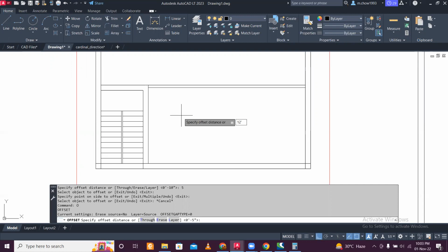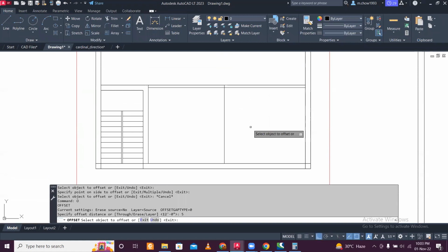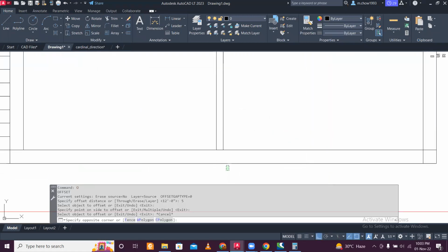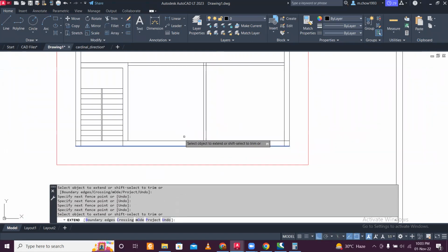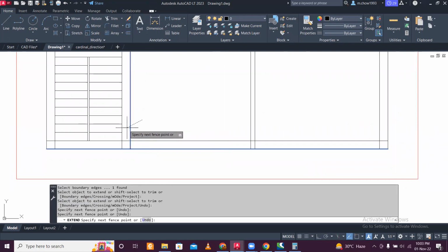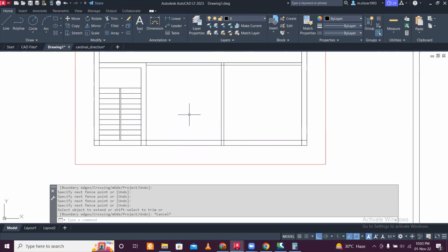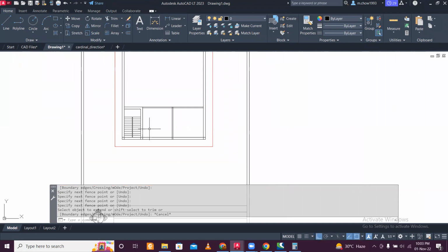Another 5-inch wall, let's say, and this is done like this. Yes, enter, and this is also select yes, enter, and then left click and select. This will be the garage door, and this is where you place the car.